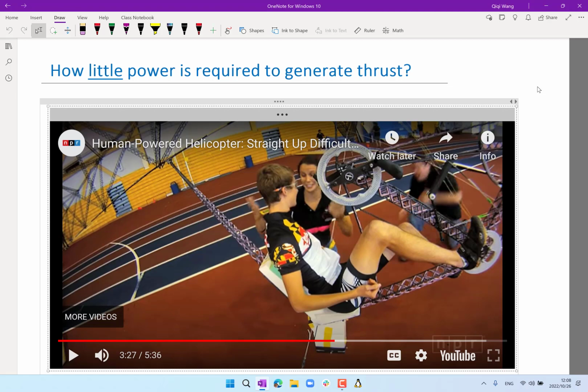You have to do a lot of calculations, adding things together. The nice thing is the principle of superposition when you are considering only potential flow. So basically you can think about all these vortices, either vortex lines or vortex rings, and add the effects together to form a flow field. Of course, you have to have a computer to laboriously add all of them together to calculate the flow field.